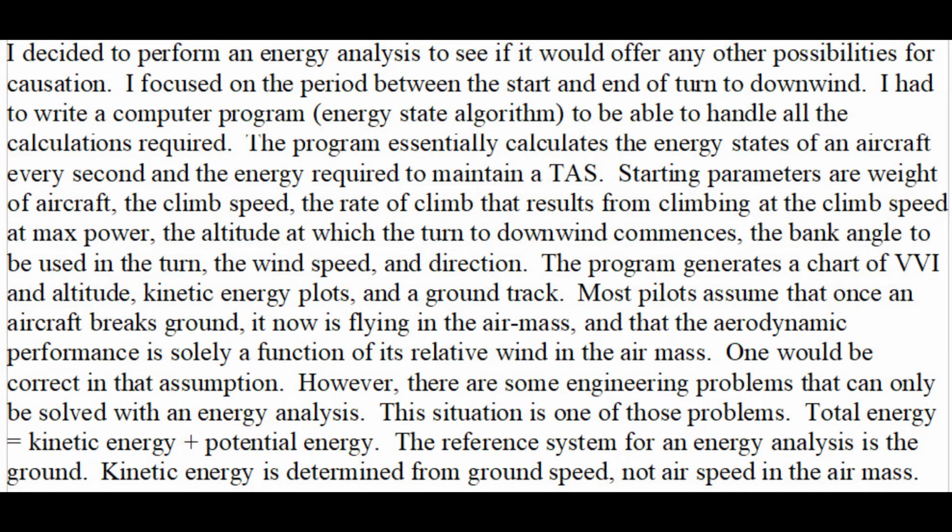I decided to perform an energy analysis to see if it would offer any other possibilities for causation. I focused on the period between the start and end of the turn to downwind. I had to write a computer program, which is an energy state algorithm, to be able to handle all the calculations required. The program essentially calculates the energy states of an aircraft every second and the energy required to maintain a true airspeed.